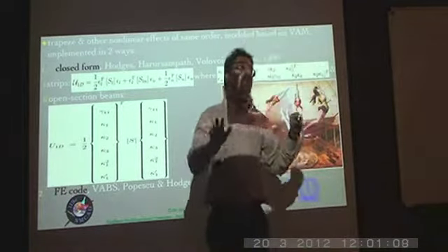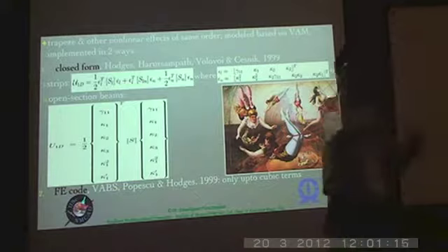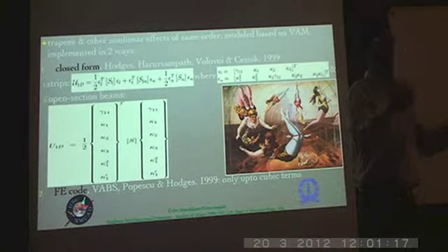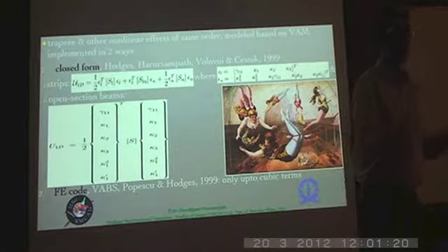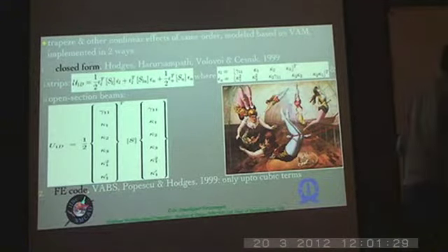Now the strain is limited by the material failure. So that is purely a material property, and that comes as an input for us in the problem because we have chosen the material that we want to use for a particular beam. So it's of the order of, let's say, a few percent. Since that is fixed, now your curvature gets fixed by that because your strain epsilon is of the order of... basically let's say the maximum strain that you get is your gamma 11 in this particular case because it is bending. So your bending strain, the maximum that it can take is the material failure value, order epsilon,